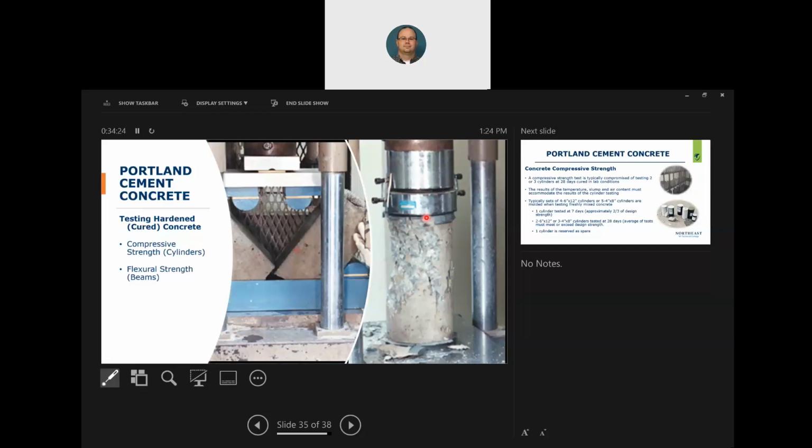Okay. Compressive strength cylinders. And then we also do flexural strength for beams. Okay. So you remember, when you look at a bridge overpass, those concrete beams, there's reinforcement in there. Concrete is weak in tension and strong in compression. So basically, when we break concrete, we call it a modulus of rupture. That value will determine how much reinforcement we need to get into there. So the concrete will always crack in tension. It always cracks, but we control the cracking. So we need to crack the concrete so we can engage the reinforcement. Okay, so that's why we make beams, especially in DOT roadways.